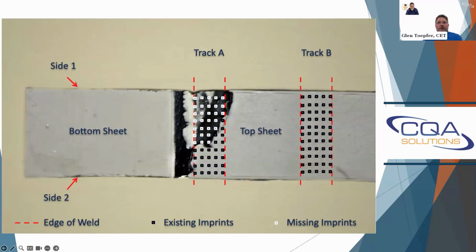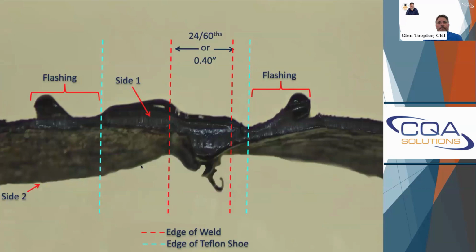You can look at your impressions on the nip roller. Some of the wedges, anyway, leave good impressions that you can actually see and count. So you can take your total number, then count up the number that's in the area peel, divide it out, and it gives you a pretty good ballpark of what that peel incursion actually is. Good enough for a field decision anyways.